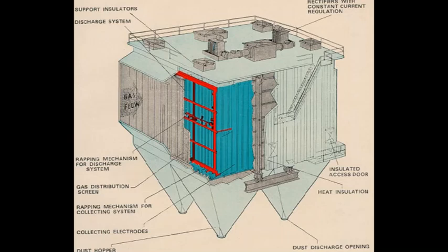We have many types of arrangement, mostly mechanical dust collectors in some of the plants, and in all the plants we find electrostatic precipitators, which is an equipment which charges the ash particles, fly ash particles, and gets them collected on some collecting plates in the electrostatic precipitator, and that is again transported to the ash handling plant and disposed in some ash dikes.